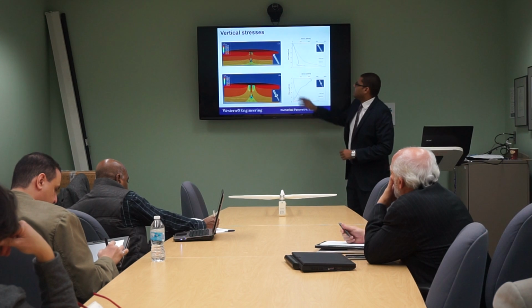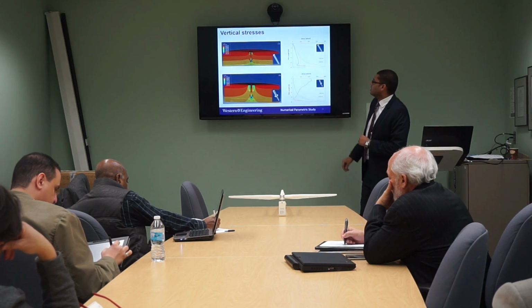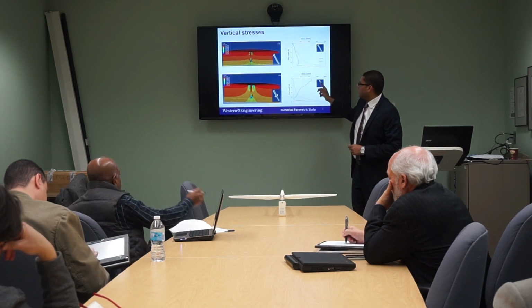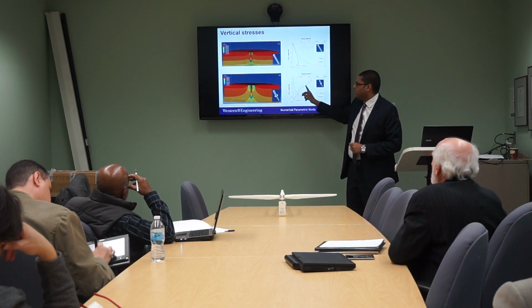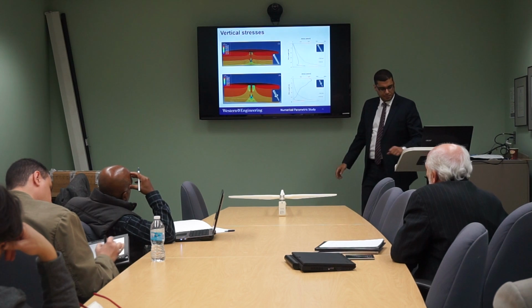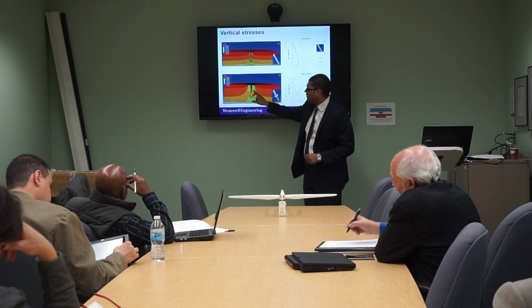From Abaqus models, we can see here the vertical stresses in the case of the pile and in the case of the hybrid foundation system, to see the effect of adding the plate in increasing the vertical capacity in the soil. We can see this effect here.